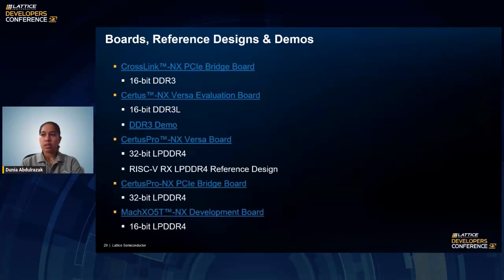For Certus Pro-NX, we have two boards available, showcasing 32-bit support, the Versa board and the PCIe bridge board. There is also a RISC-V to LPDDR4 reference design available for the Versa board, showcasing FreeRTOS booting from LPDDR4 memory. For Mach X05T and X, we have the development board with 16-bit LPDDR4 memory on board.